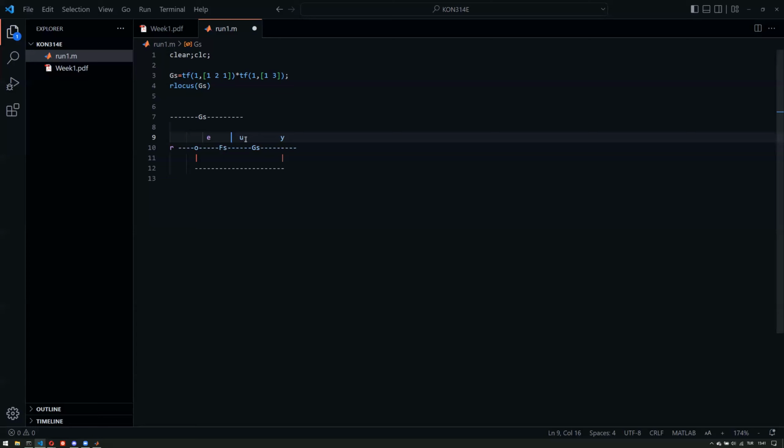We will try to come up with structures and designs that will ultimately just change how things behave. Here in this case, we have a certain G(s), and I can already tell you that if I apply a step to G(s), I'll get something that will not track its input. The reason why I say that is because we have the final value theorem where I can just plug in s equals 0, or in other words, multiply with s and the step function 1 divided by s, and then take the limit where s tends to 0.